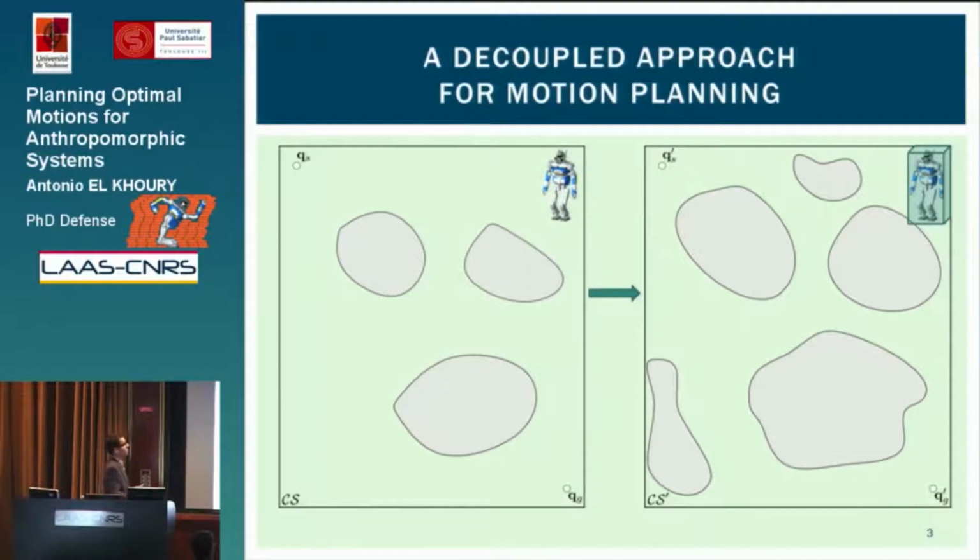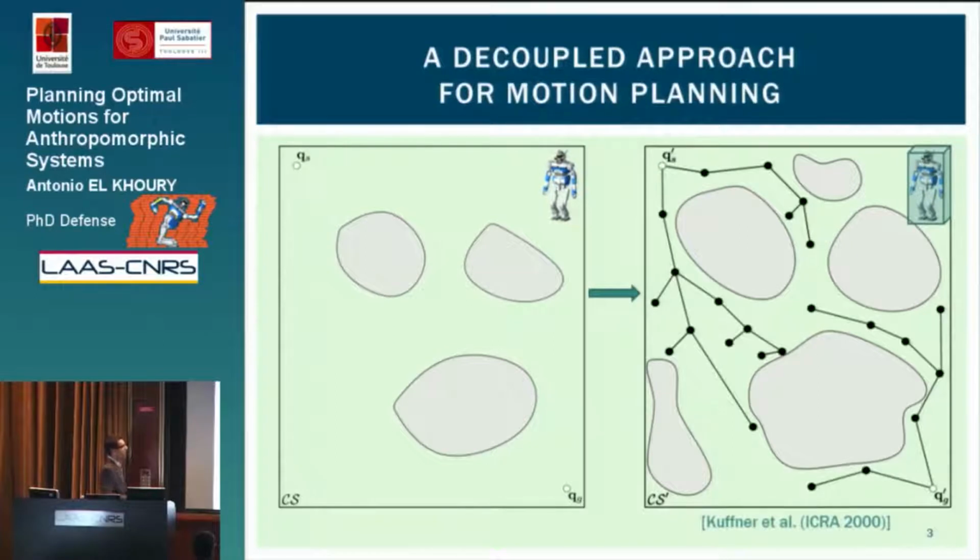Now, in this particular space, once we are able to define it, we can rely on sampling-based planners, which are able to rely on randomness, so on sampling random configurations in the space, and on very fast exploration of the space, even if it's highly dimensional, in order to find a continuous path this time, so not a motion, not a trajectory, a continuous path linking the original configuration to the final one. Here it's important to note that we do not have any time parameterization yet. There is no notion of time. The S parameterization here